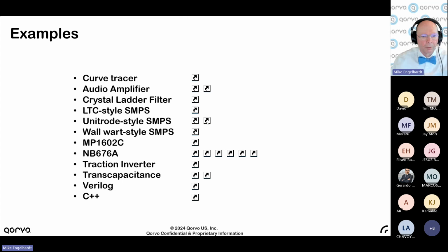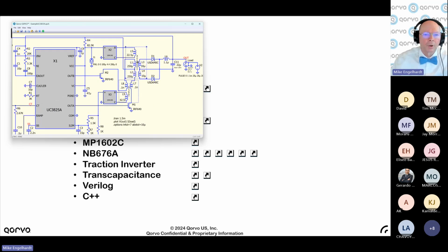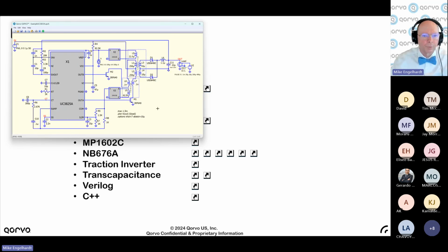Here's the completely archetypical Unitrode part, the thing that was used for offline converters with push-pull forward converters. This transformer is the push-pull part. This transformer is a current transformer. The switcher is actually voltage mode, but it has current protection because you're going to monitor these currents and then kick the ramp high so you terminate the cycle when you have too much current.